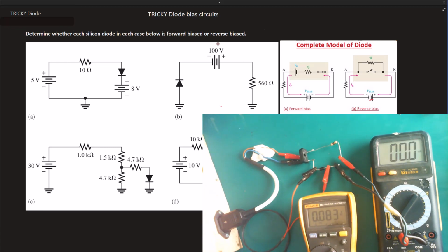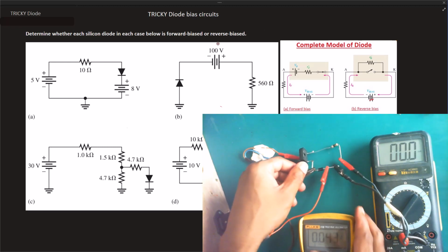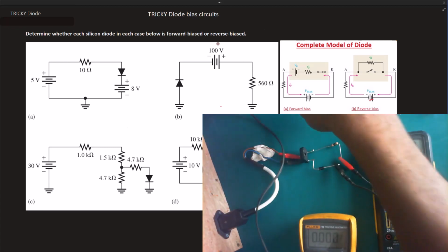Now here we go. Let me turn this on and then we start monitoring. Now we can see we're getting 146 milliamps. The voltage across here is 7.73. Now the resistor is smoking. This resistor is suffering here, it is actually bearing the consequences of what's going on here. Now why is the resistor smoking? Obviously because there is too much power across that resistor.